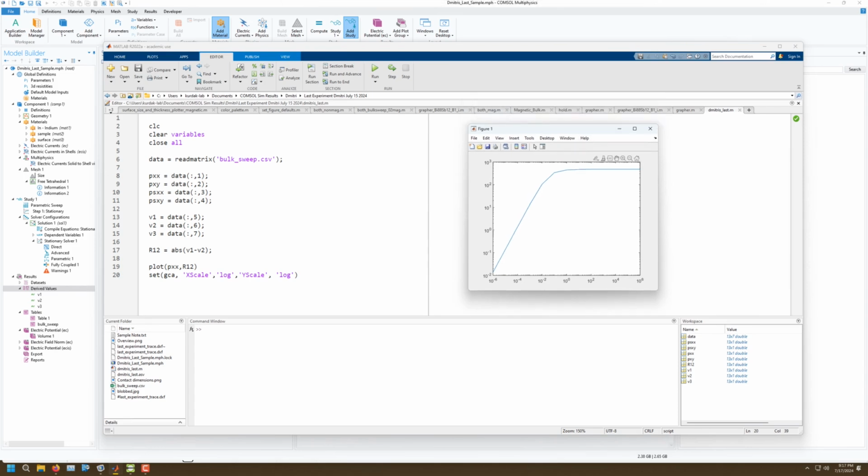So this is the bulk dominating part, and eventually when the bulk gets too resistive, the surface dominating regime takes over and it saturates at the like 500 ohm part that we found. So technically we kind of have all the bulk stuff we need.